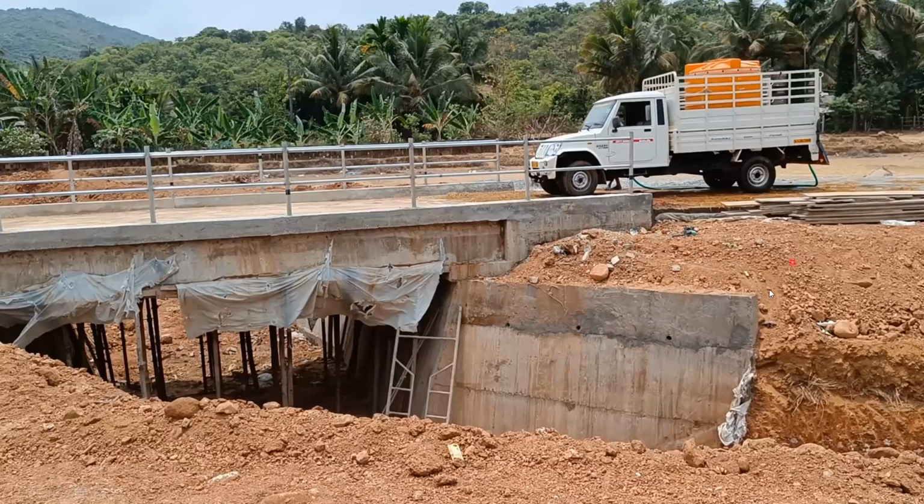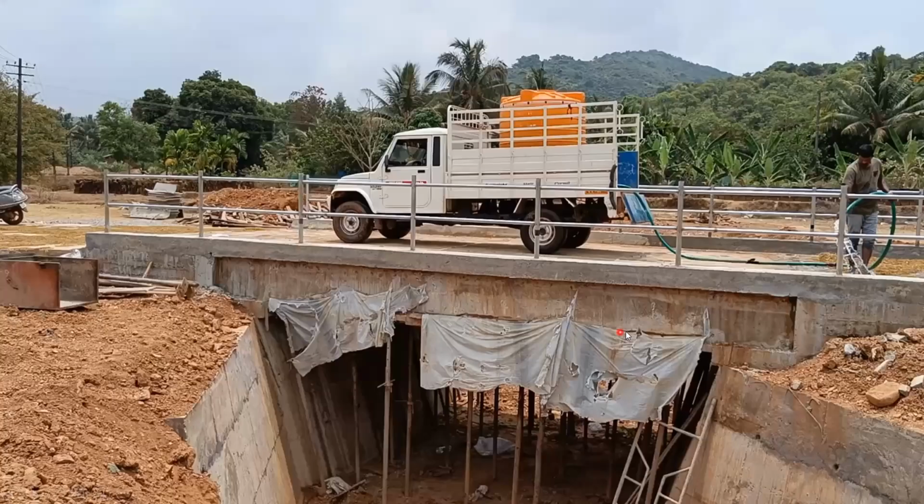So whenever there is water in the soil, that water will pass through this. As a result, whatever pressure is created in this area will be released. If I don't give this, a lot of pressure will be created because of the water stored in the soil, and it will put a lot of lateral pressure on this. Again, there may be a chance of cracks and all. So that is why we give these things. Okay. Now you got an idea how it was completely created.